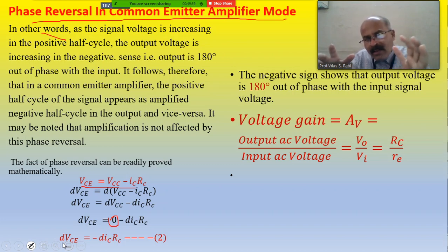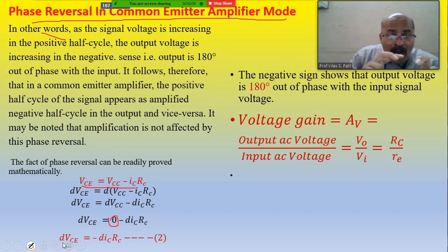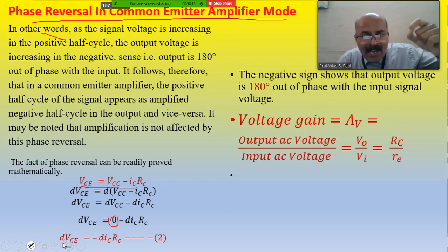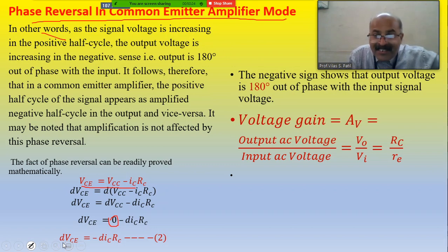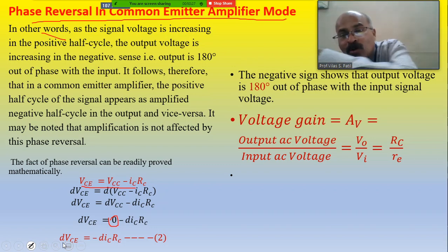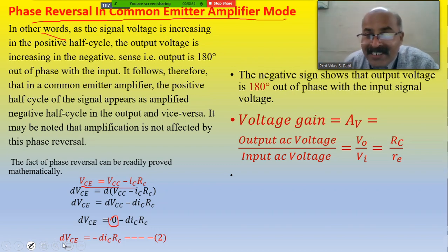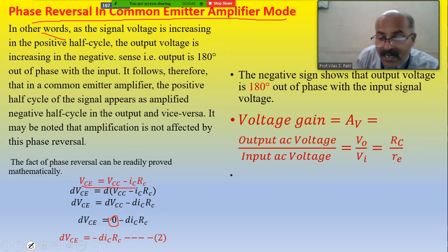But this basic single stage common emitter transistor amplifier circuit not only amplifies the voltage, but according to the definition of the transistor, which was studied in the introduction, the transistor can transfer the resistance from input to output. The input resistance, friends, will be very small resistance re, that is the emitter resistance of the transistor, and the output resistance Rc.